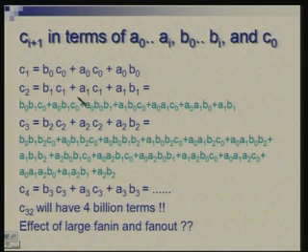Also we expand, because we want to ultimately have a 2 level expression. You could have left that in parenthesis, with B1 plus A1 within a bracket and the expression for C1 in another bracket, and then say that these two are ANDed, but then we are increasing the level of logic.